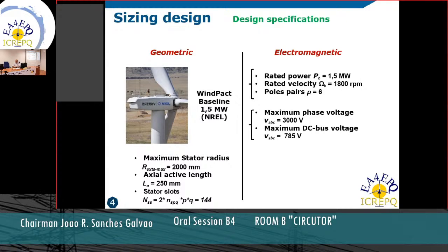This value is also taken from another experiment for a permanent magnet machine that was designed specifically for this particular wind turbine. A maximum flux density of 1.5 Tesla is set to take into account possible magnetic saturations in the machine, and a power factor of 0.8 to ensure maximum efficiency.